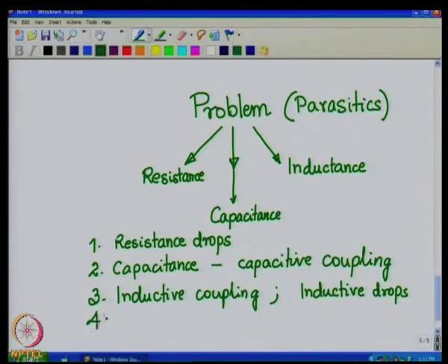And then you have another problem, the problem of reflection. At high frequencies, when you use high speed digital circuits, the clock frequencies or the waveforms in most cases are pulses. They have very fast rise times, and these fast rise times mean very high frequencies, and the tracks will behave like transmission lines. Because of these transmission line effects, you will have reflections both at the sourcing side and the destination or the load side, and the waveforms will not be neat pulses, but due to the reflections it will vary, and you will have overshoots and undershoots, as we will see later on.